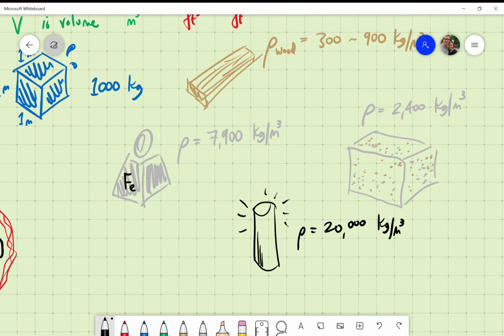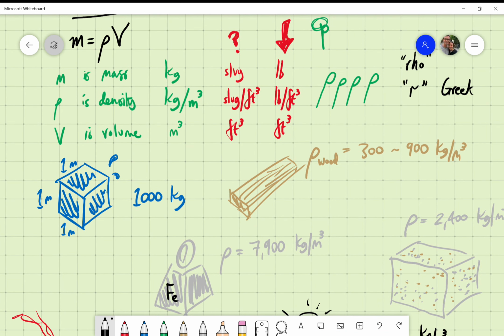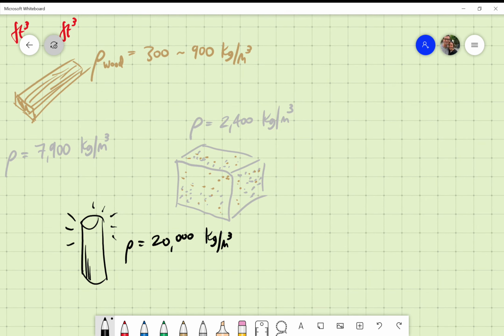Now, when it comes to calculating the weight and the mass and the volume of these kinds of things, this is the interplay here. What you really need to do is just use some basic geometry. So look, here's our concrete block. Let's say this concrete block is 2 meters tall, 5 meters in the other direction, and 3 meters in the other direction, and it's a cuboid. So you know that the volume is length times width times height. So you throw all those things together and you get 30 cubic meters.